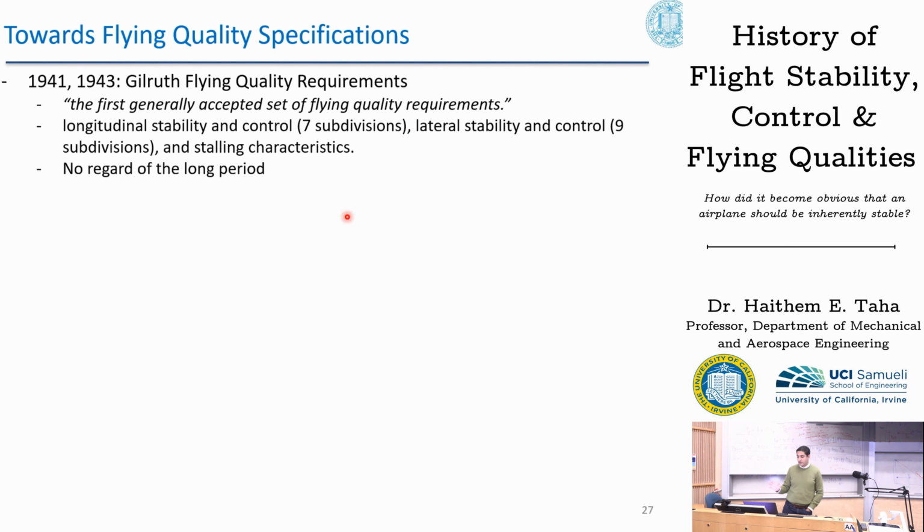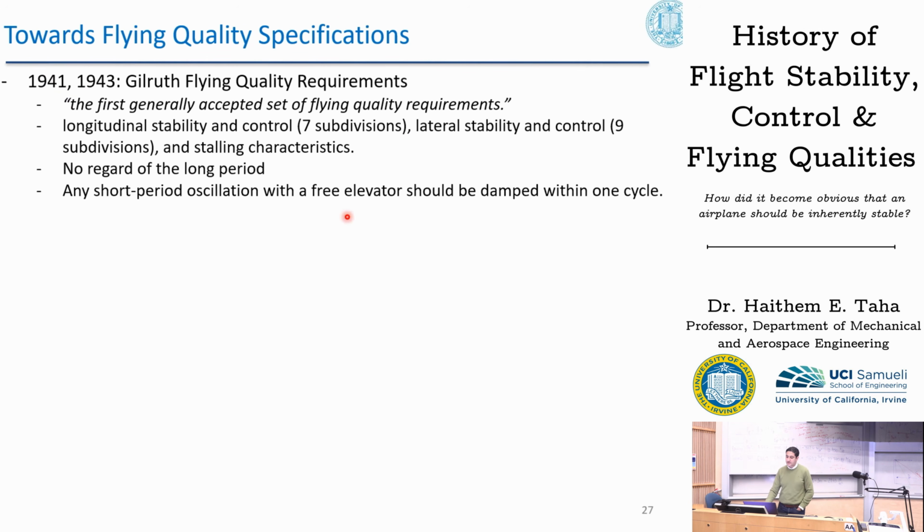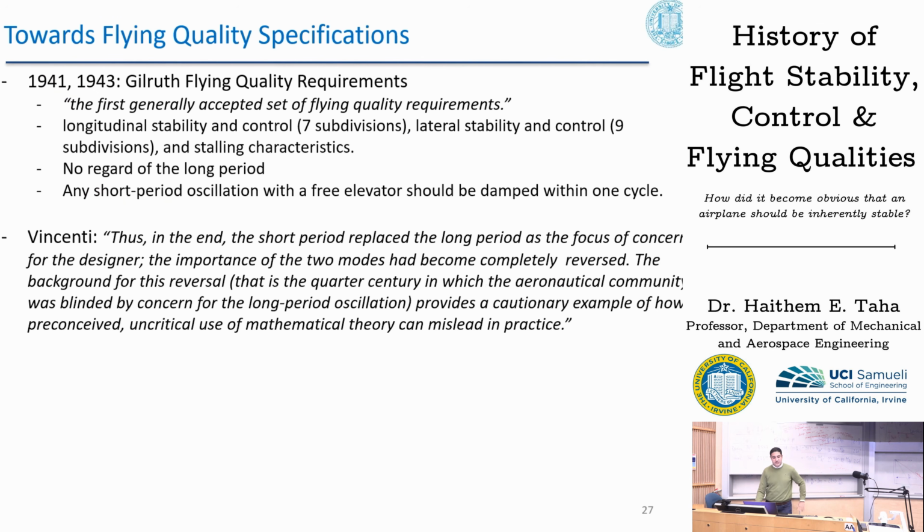No mention of the long period mode. It's of no concern to pilots. And instead, any short period oscillation with a free elevator should be dampened within 1 cycle. So this came out of this flight testing program. So Vincenti commented here, thus, in the end, the short period replaced the long period as the focus of concern for the designer. The importance of the 2 modes had become completely reversed.